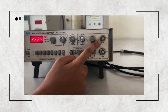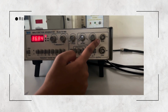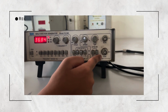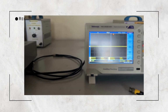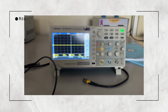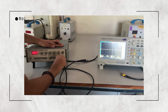So this is basically the TTL probe. The TTL output will produce a 5 volt square wave with a frequency equivalent to the value that you programmed into the function generator, and this is the function probe, which is basically used to generate the signals that you would further connect to the digital oscilloscope. So here I will connect the probe with the digital oscilloscope that is placed right next to the function generator.